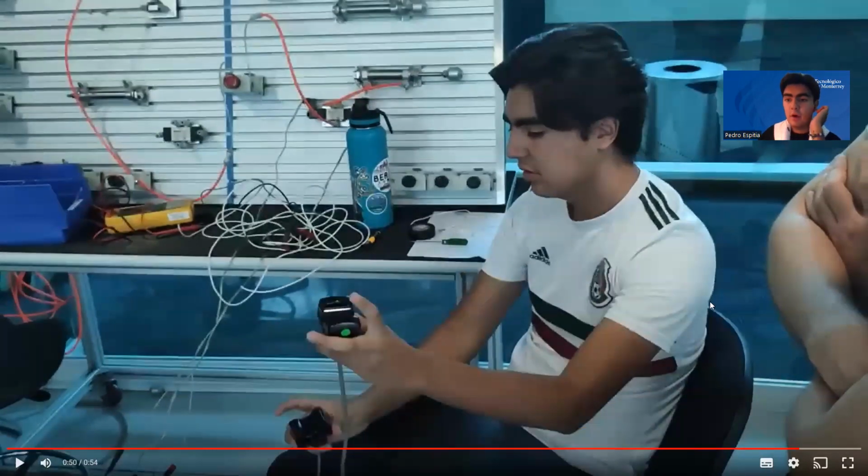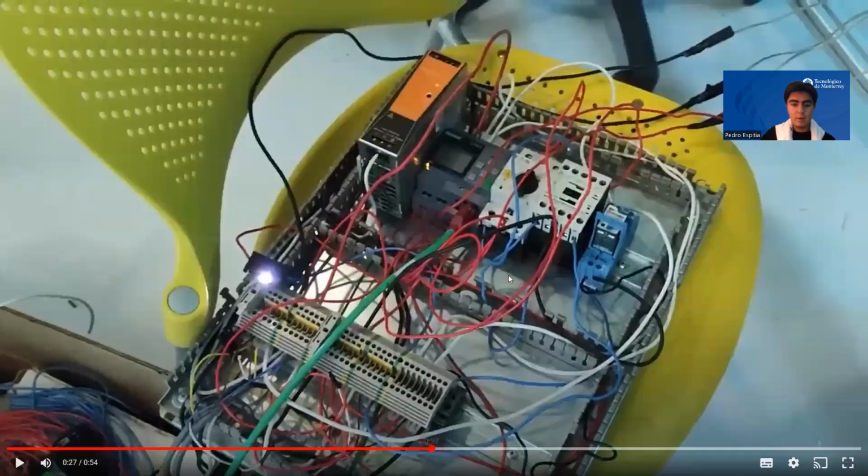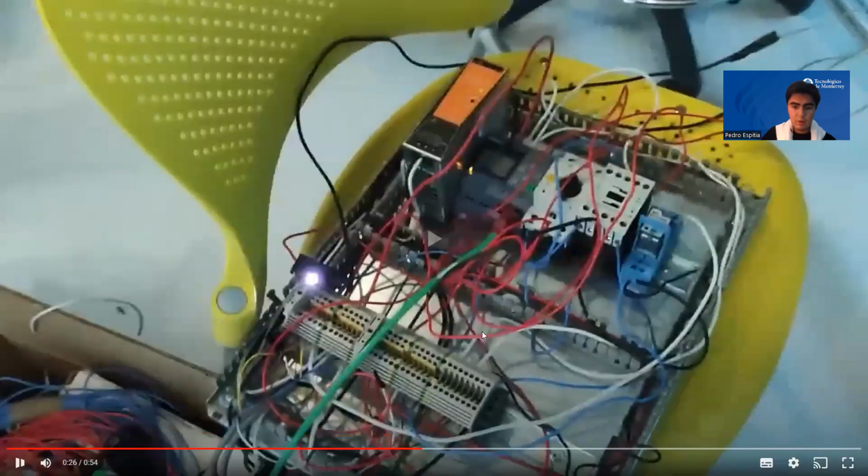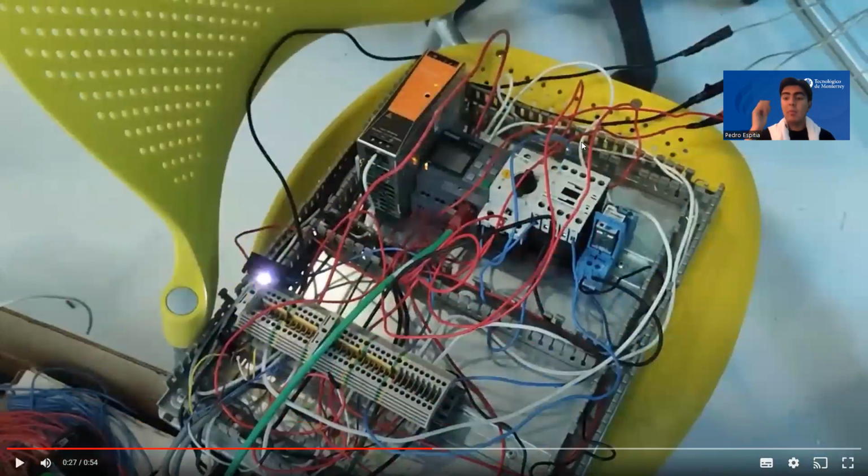Now the functionality of our whole system I will show you in the control cabinet. Here we can see that the optotouch sensors are connected to the line and to the neutral, depending on the color of the cable. If I remember well, the brown one goes to the line, and the blue cable goes to the neutral. And with the normally open contact, it will connect to the free clamp that connects directly to the relay.